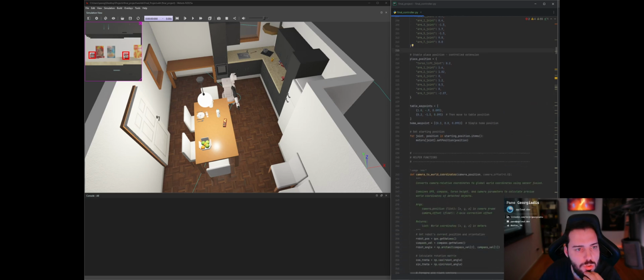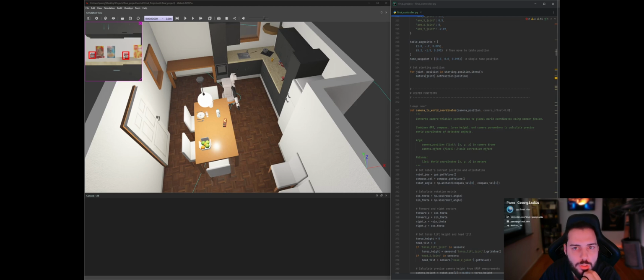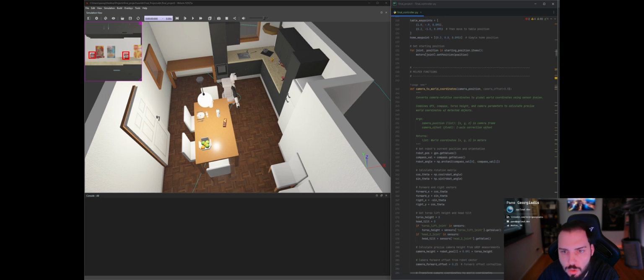The place position is used to place the jar on the table correctly, and then we have table waypoints. We're moving down -y from where the location of the jars are, you'll see, and then we're moving over to the left or in a -x in order to move to the table, and that's just ensuring that the direction of the robot and its arm is facing the table. You could have done this in multiple different ways. I just found that this was the most simple way. You just put a location that is south of where the robot is, and then towards the left of the robot, and that ensures that its arm ends up over the table.